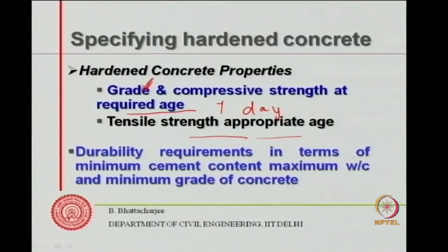So durability requirements are specified in terms of some prescription of minimum cement content, maximum water cement ratio, and minimum grade of concrete, etc. All right.